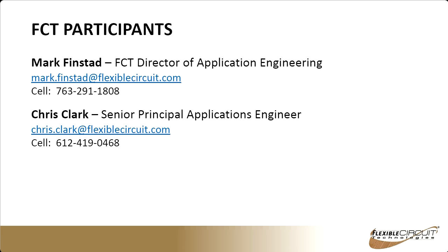Another question: if the power is larger than required, is the flex fail safe? We can put fuses or thermostats directly onto the heaters. We can also etch fuses in. That's less common, but that is a possibility. That would pretty much trash the system, though.